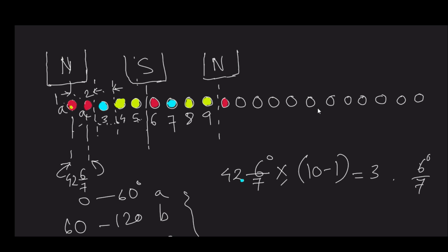This is slot number 10, so it is for 10 slot. What we are getting is 385.71 degree. So 385.71 means next span, this is 10 slot. 360 to 420 will again be occupied by A. So we will give this to A.